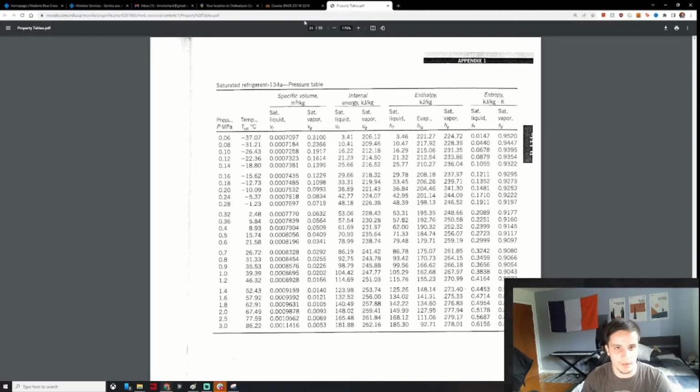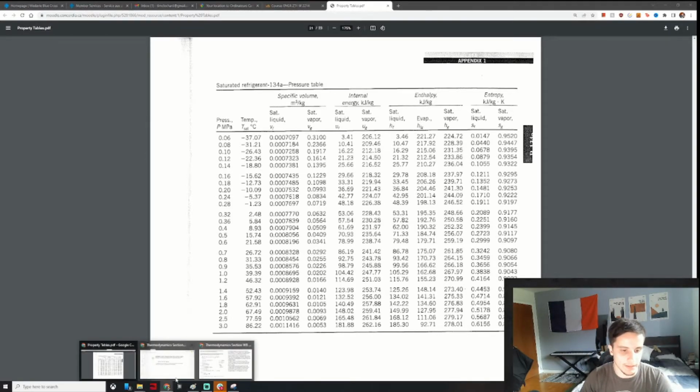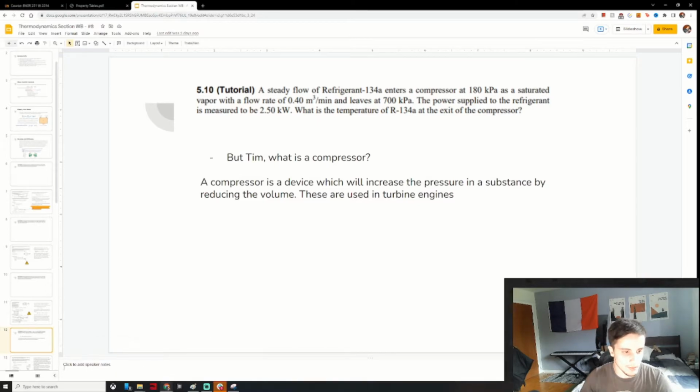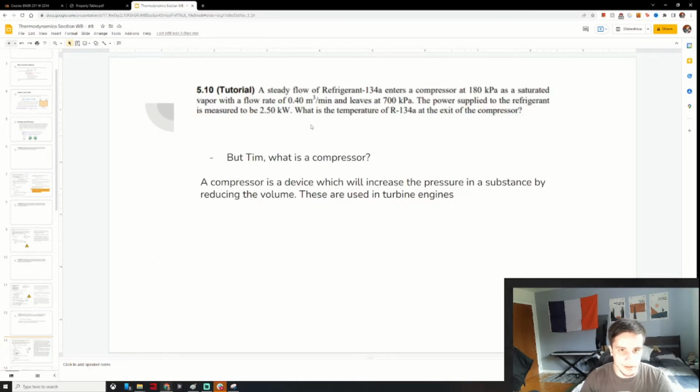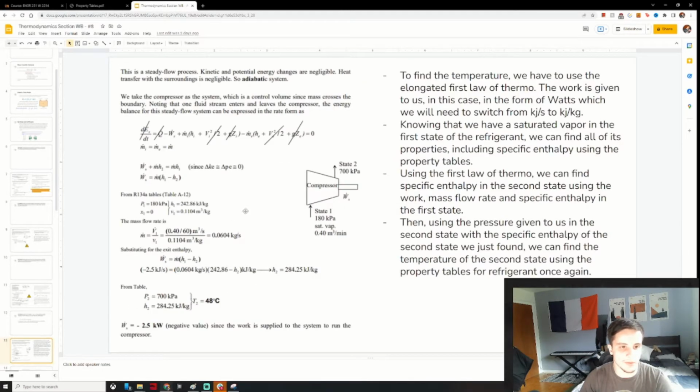Okay, well, that's completely wrong. Let's take a look at the correction. I didn't see that there. So here, just to go over it, they say saturated vapor, so that means 100%, X is equal to 1. But in this case, they give us a pressure, the right pressure, 100 kilopascal. But they say X is equal to 0, and then they have a specific volume that's wrong. Well, it's very close to what we have. So this correction actually is wrong.